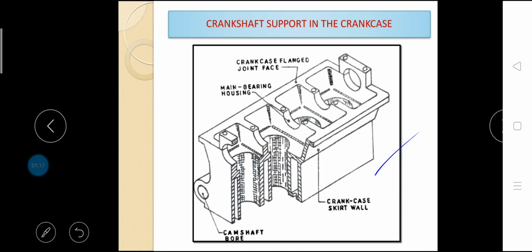The cylinder block is basically a casting product. Both monoblock and individual cylinder casting techniques have been tried, but the former has proved more useful due to the following reasons and is therefore being employed universally. The problem of having good water-sealed joints is reduced because of reduction in their quantity. More positive water circulation is achieved. The manufacturing operations like machining the joint faces, cylinder boring, etc. are simplified. Closer cylinder spacing is achieved, thus reducing engine size. An assembly far more rigid than in the individual cylinder construction is achieved, thus reducing tendency to vibrate.